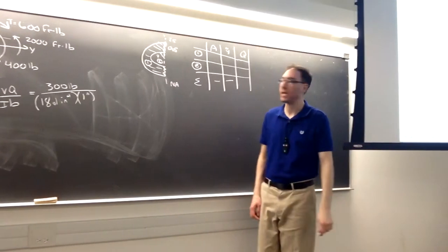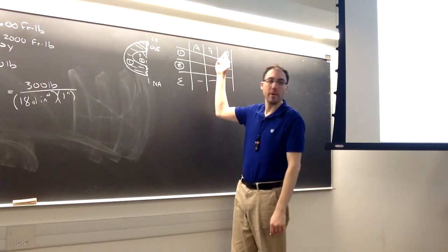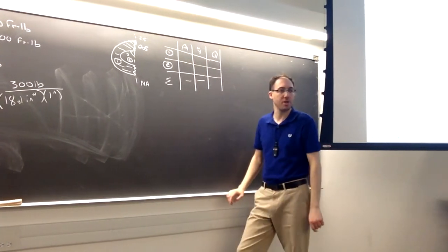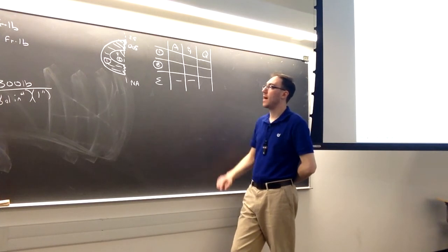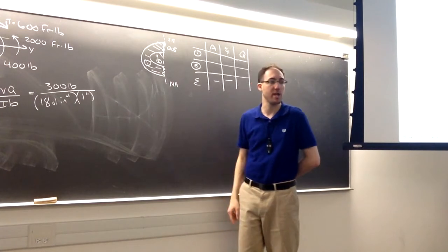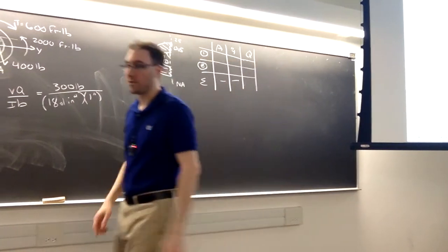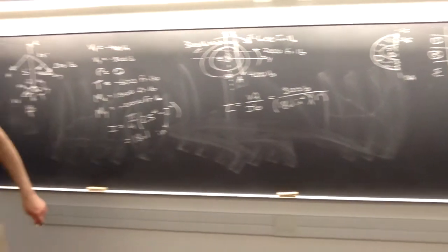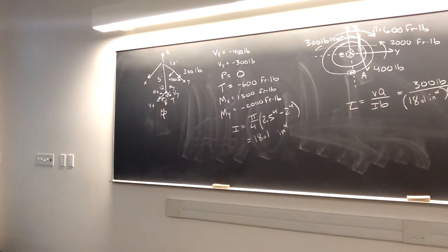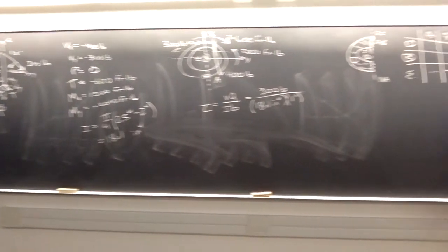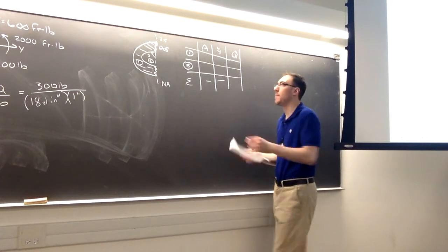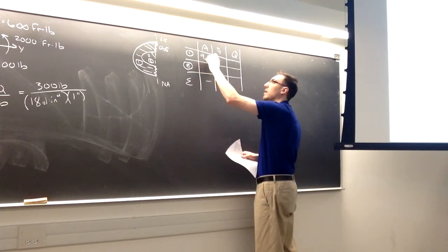Right, so if I'm interested in finding Q, Q is just A times y tilde. So all I want to know is the total Q for this shape. I can break it down into a solid hemisphere and then a cutout hemisphere, shape number 2 here. So for shape number 1, its area is going to be pi times 2.5 squared over 2, since it's a half circle. So its area is going to be 9.82 inches squared.